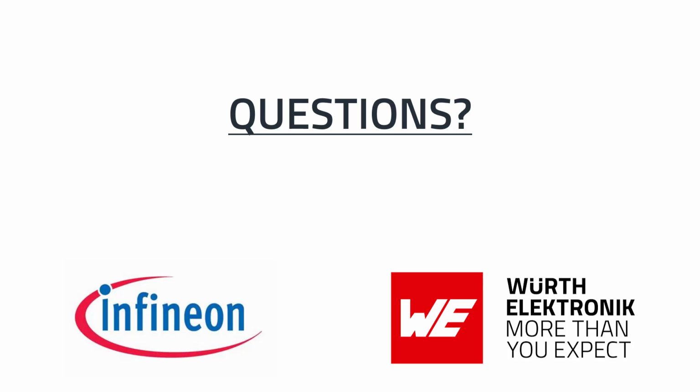And this is the startup behavior I mentioned here, that it impacts that application portion. And therefore, either we always have a good base load on the system, or we have a higher leakage inductance to reduce the impact of this voltage overshoot at light load. We have this chapter also in the data sheet of our product. But again, it's not only because of the transformer, it's not only because of the switch, it has an impact of all the surrounding components required for such a power supply, and it impacts all open loop solutions out there.